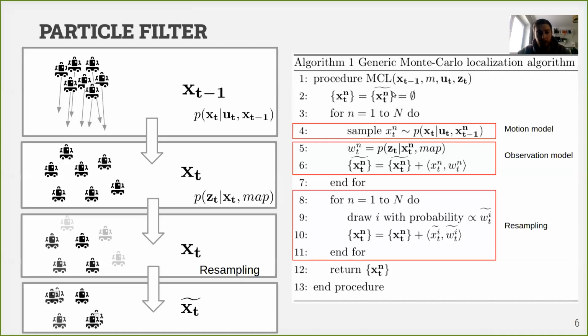So see what we are doing here. Imagine we are starting with, let's say, 7 particles here. So at the first or initial moment of time, we somehow initialize our particles. For example, if we have a map, imagine this rectangle is actually our map, right? So we can generate 7 hypotheses on where our robot is in this map.